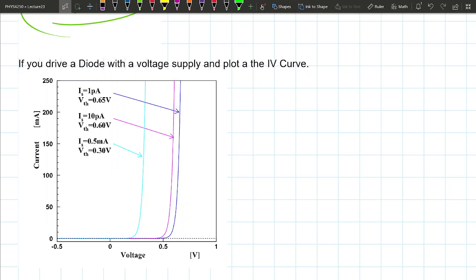So this is a current versus voltage graph, right? As you apply close to 0.6 volts, let's say at 0.5, you start to see a tiny bit of current because you're decreasing that depletion zone between them. There's just some thermal fluctuation that allows the electrons to cross. But it turns on fully at 0.65 volts, right? This is what this blue line is. At 0.65 volts, basically the current will go to infinity, okay?